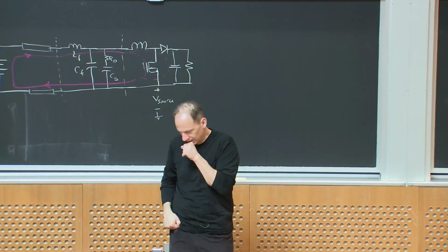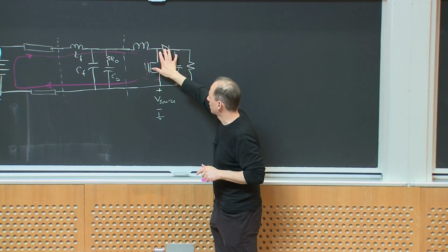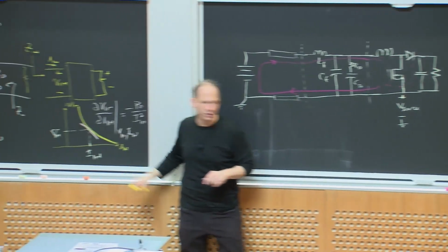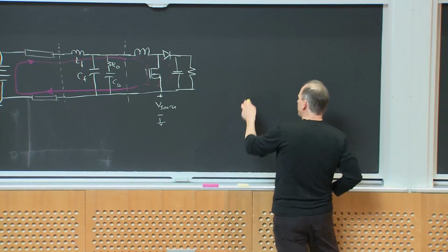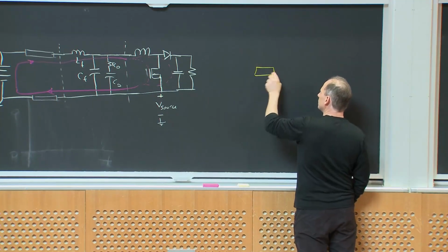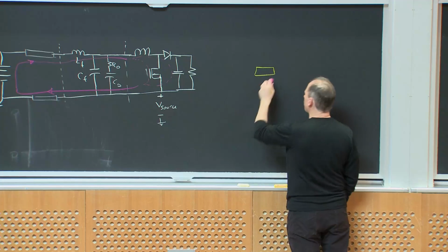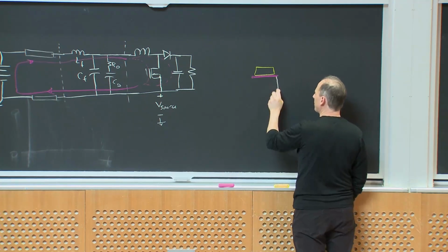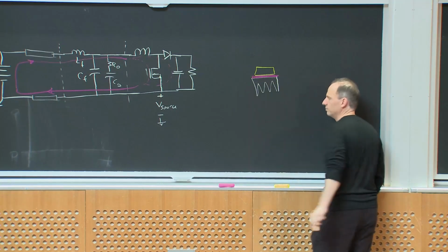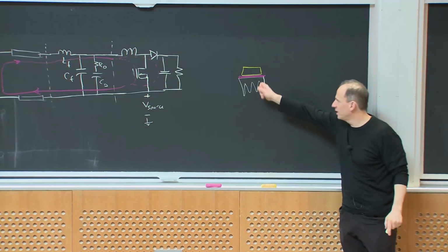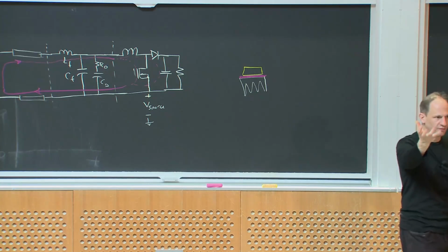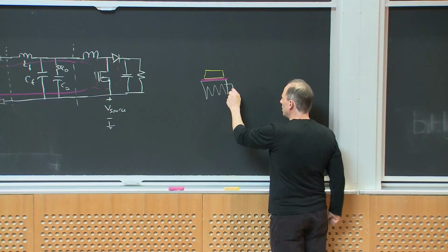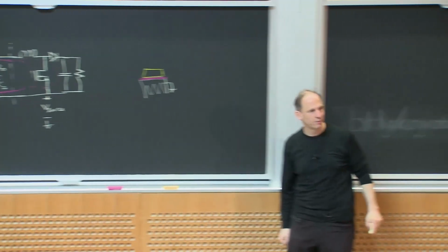But if I think about it, I've got to heat sink the switch and the diode. So let's just think about the transistor, and let's remember how we do that. So here I have my transistor, and then I'm going to put down a thermal pad. On the other side of that thermal pad will be whatever I'm heat sinking the device to. What I'm often heat sinking the device to is either the case of the power supply, and that case of the power supply is often connected back to ground. In fact, sometimes you'll use the case of the whole thing to be ground.